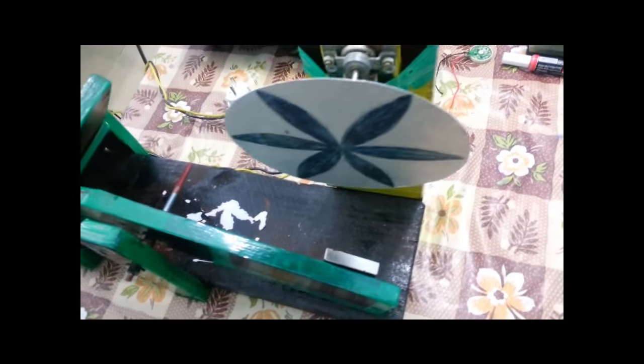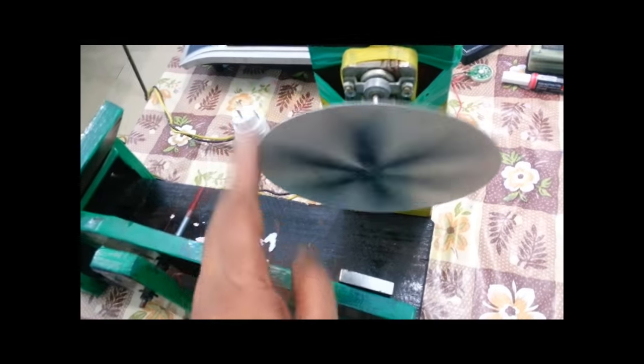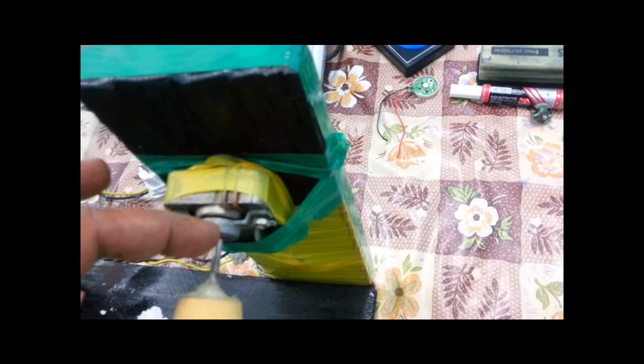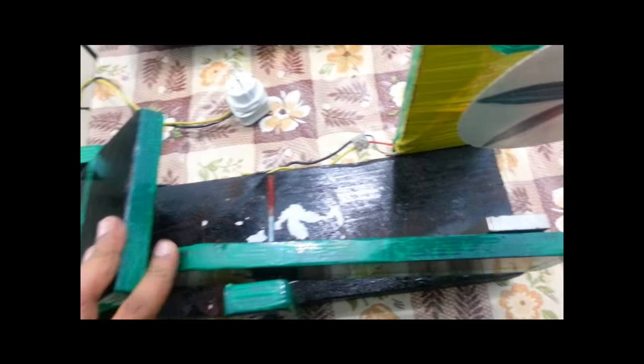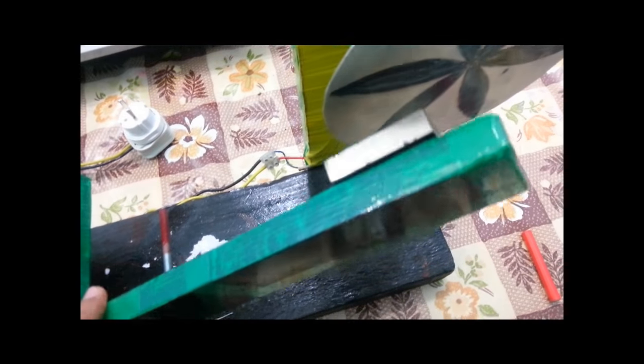Another device we have here is an electric power brake system. This electric power brake system consists of an aluminum drum. It is connected to a motor, and there is a strong magnet here. It is connected to the pedal of the brake system. So if I apply force here, the brake magnet will lift up, and when it comes closer to the aluminum drum, and if the aluminum drum is rotating, it will produce a change in magnetic field. Because of that, eddy current will be induced in it. Due to that eddy current, it will experience a torque in the direction opposite to the rotation, and because of that, it will try to stop. I will show you that working.